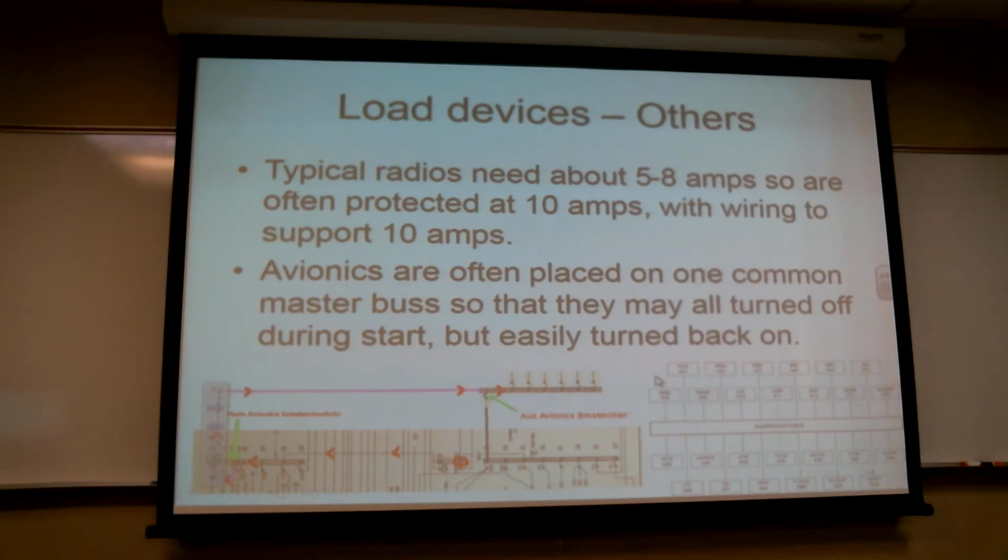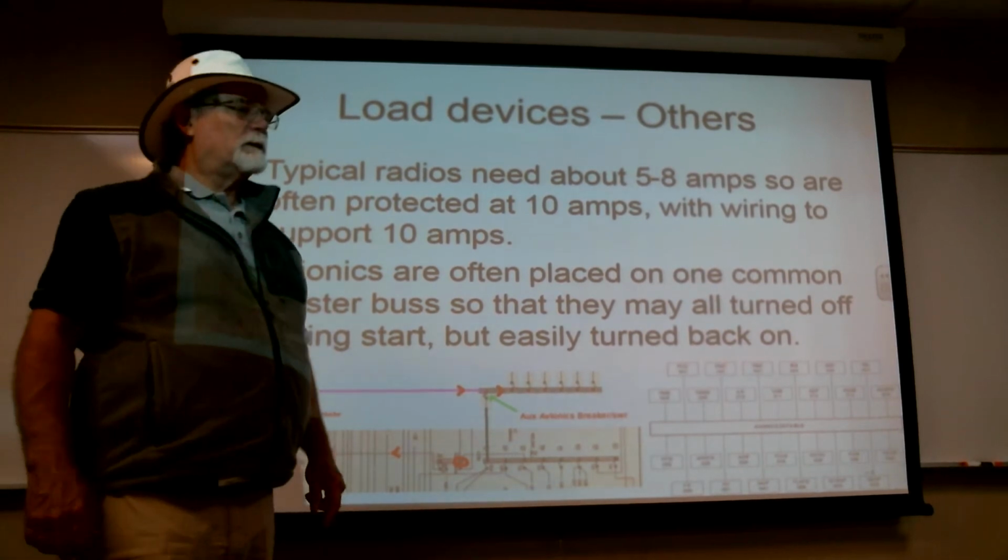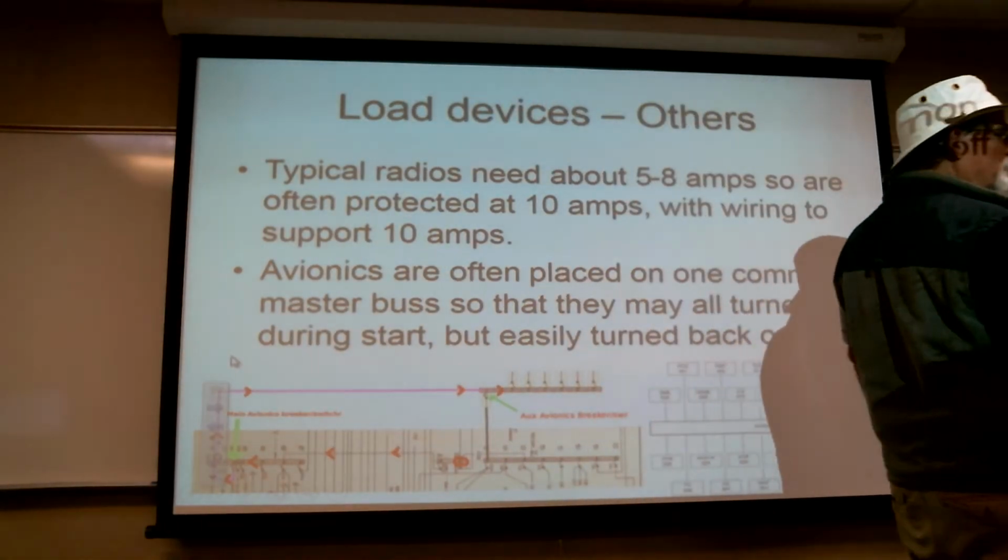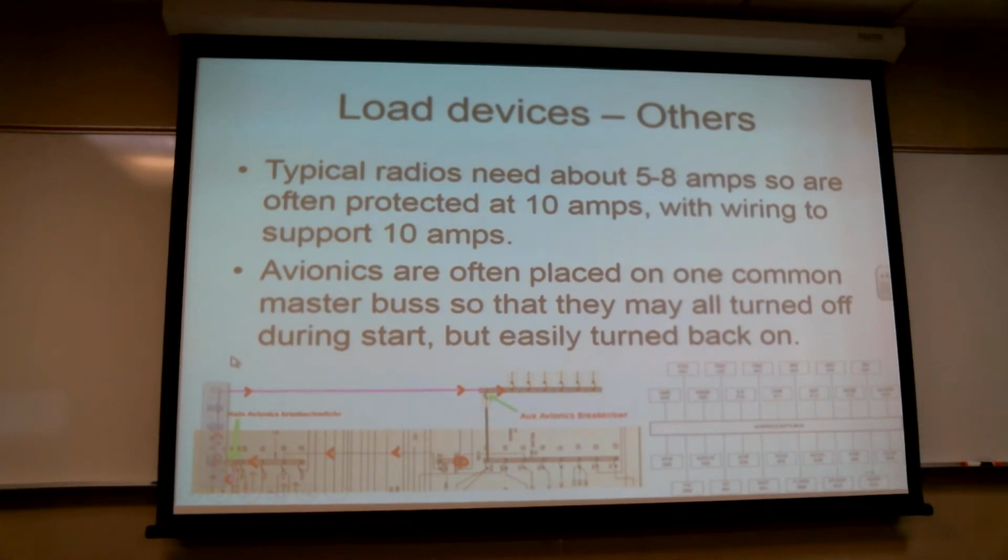And I think we've talked about this in the past, but good question. Seems like there's more damage that can be caused during the shutdown more than the start, right? Because of the inductance, the coils collapsing. So yes, but the damage is probably most likely going to come from a very large motor that typically gets used at the very onset of the use of the airplane, i.e. your starter motor. So that would be one thing you'd want to avoid, having other things turned on.